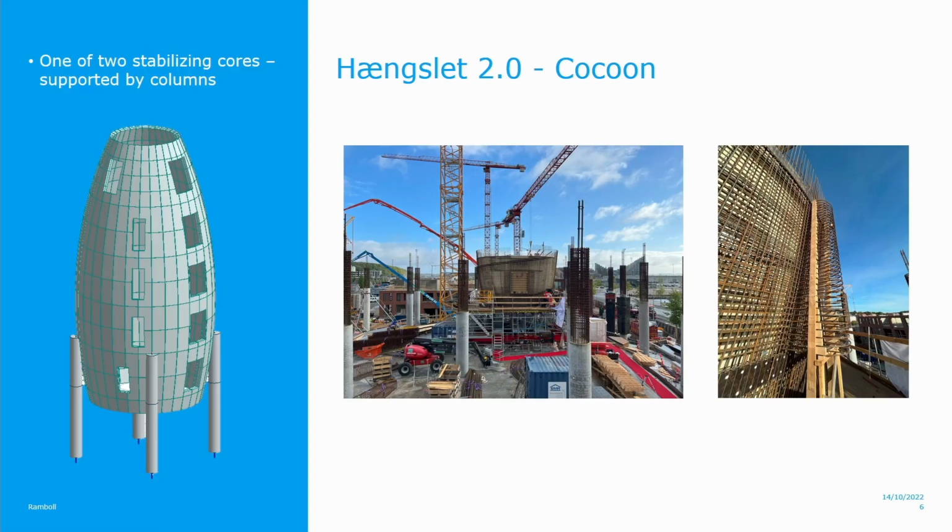And yeah, we also see our columns quite large. The reinforcement is through 2 stories because there was no geometrical space to do the laps in the section without losing too much effective height in the cross section. So that's why they are so tall, the reinforcement still.